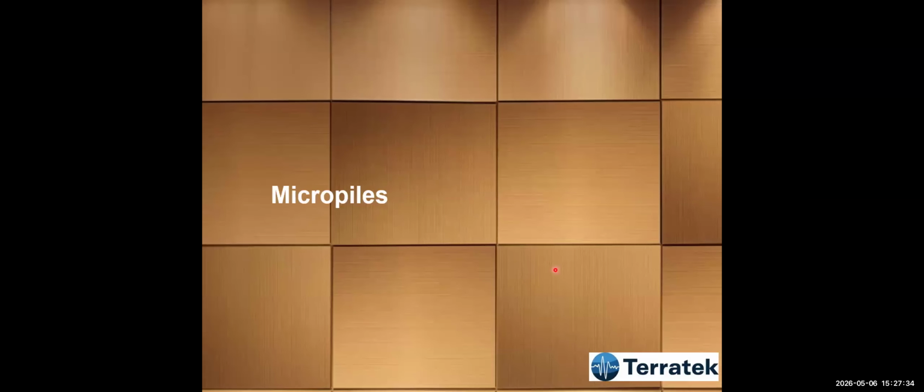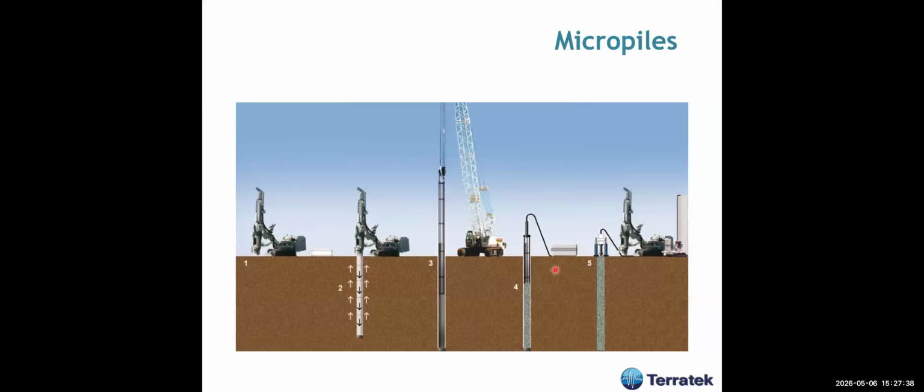Let's talk a little bit about micropiles now. Micropiles are usually for small loads, not very high loads, but sometimes when you have rock, for instance, if you have boulders in the soil profile, micropiles are very important because they can be drilled through boulders, through rock.